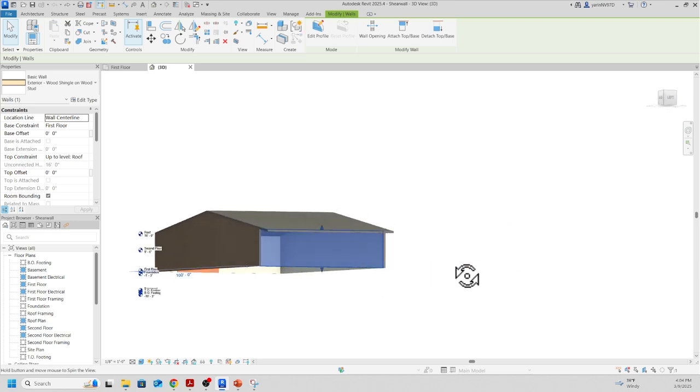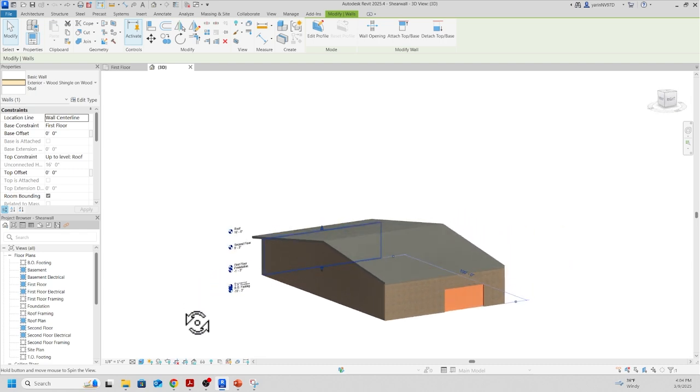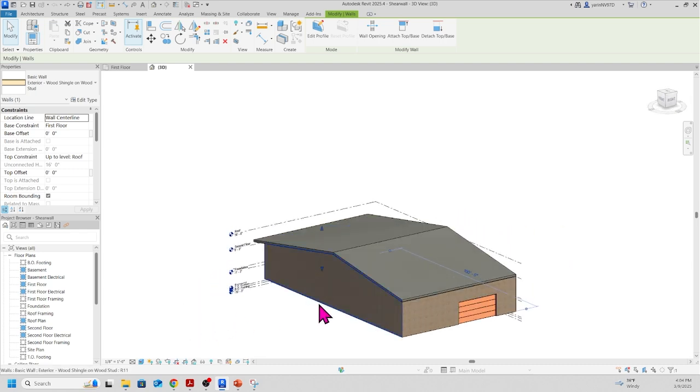What happens is that we have the earthquake Fx force coming in at this angle and in the other angle, so that's why I want to make these shear walls. The Fx is coming this way and Fx coming that way. So we design these two walls to make them shear walls. If you want to know how we calculate these loads, let me go to the PowerPoint for a second.